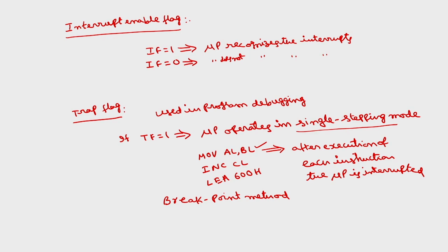This is the third operation we are discussing, the internal data operations. The first one is storing the 8-bit data, for which we need various registers. The second one is performing the arithmetic and logical operations, for which we need a single ALU. Then the third one is testing for conditions. In testing for conditions, the microprocessor needs a hardware element called the flag register. So, I have discussed the different flags of the 8086.